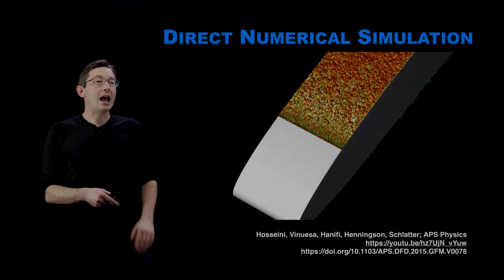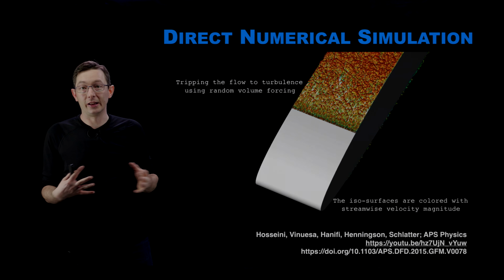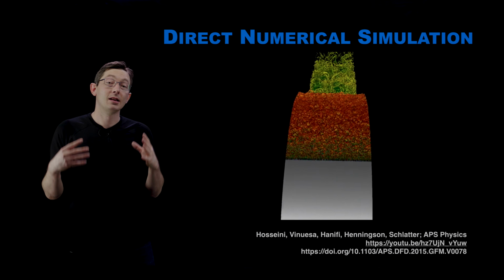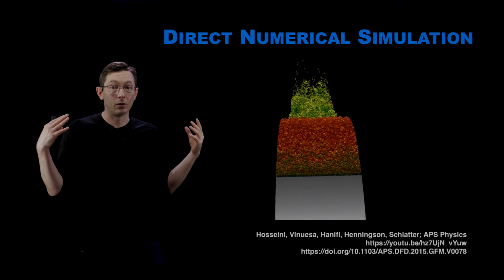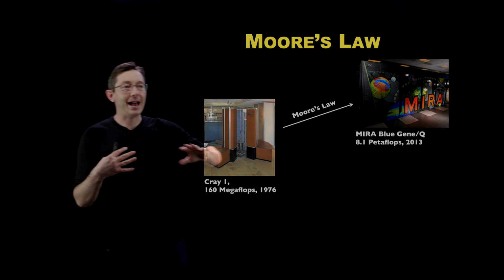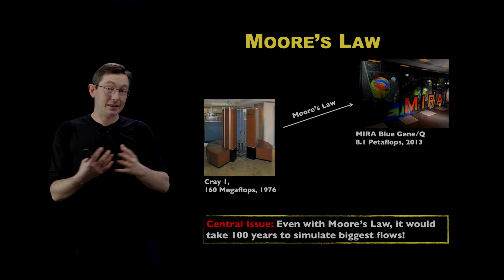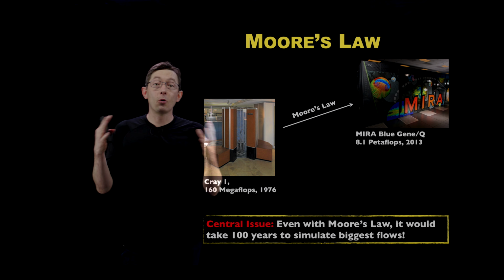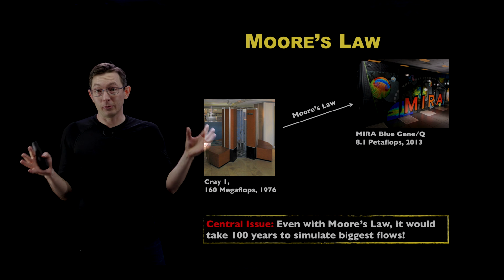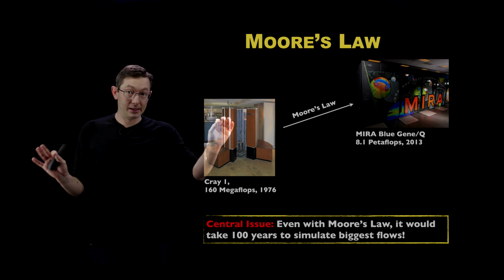Okay. And so typically it is too expensive to run direct numerical simulations or simulate all of the scales of the Navier Stokes equations all at once for something like an aircraft or a ship. Okay? And so even with Moore's law of exponentially growing computer power, it will still take, at this current rate, 100 or more years to be able to simulate the largest scale turbulent problems at all resolutions in space and time. And that's just for one run of this simulation.